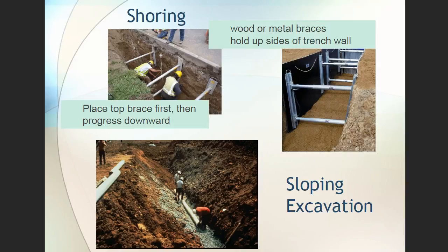Shoring. Okay, so shoring is basically the same as shielding, except it's put together in pieces. And you always want to start at the top and work down because of cave-in situations. So sloping excavation, you can see on the bottom picture the slope. Well, actually, the one on the left is legal. The one on the right is not, because see how it comes down and then it drops off real sharp? It needs to be a 2-to-1 slope. And again, this is going to depend on your soil conditions. If you're in really bad soil conditions, sandy, that kind of thing, you're in a much more susceptible area for cave-ins.